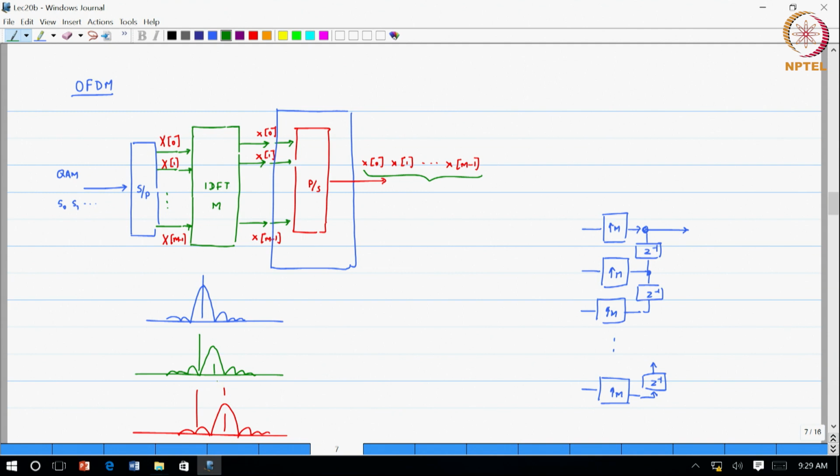So, for each of these, we said that you can do power allocation, you can choose not to use a particular channel if there is interference. So, lots of interesting things that you can do with OFDM. Again, those are things that you would have already seen in the communications course. What we are looking at is to give a signal processing, and in particular a multirate DSP interpretation for the OFDM for the generation of the frequency division multiplex signal. In our terminology, it is a transmultiplexer, and OFDM actually is a transmultiplexer in the true definition of the word.